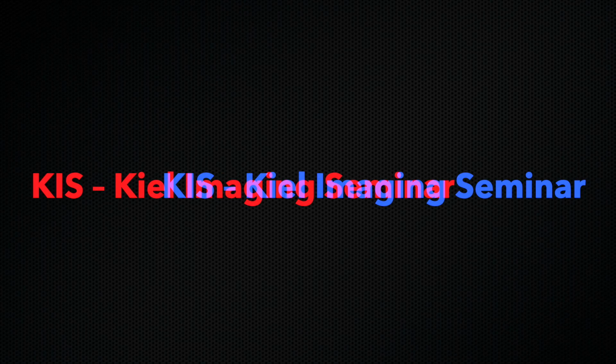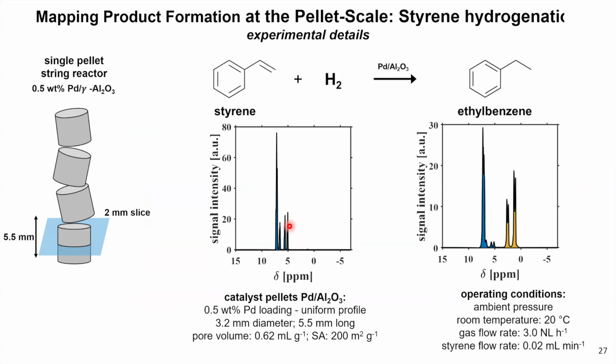Right, I'm going to move on now to thinking about reaction, and just a couple of slides to start with, very simple, looking at essentially single pellets. It's a single pellet string reactor. We've got 4 pellets sat on top of each other, and these pellets are porous. They've got a catalyst inside them, so we're expecting reaction to go on inside. The simple reaction is styrene hydrogenation. So we've got styrene and hydrogen as a feed over palladium on an alumina catalyst, which should form ethyl benzene.